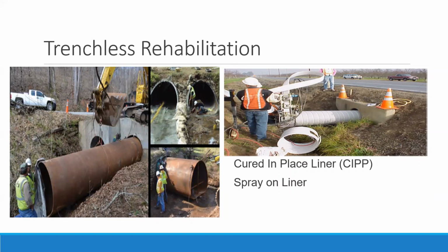Second, we've got spray-on liners. Spray lining occurs when the structure of the culvert is sprayed with a variety of different liquid products. This reline method is typically less expensive, but does not provide the structural support of other slip line methods. Spray lining materials can include polyurethane and cementitious materials. Next, we would have vinyl wrap liners, which use a specialized machine to install a spirally wound vinyl material into the host pipe. You can see from the picture here where those sections would be fused together as they pass through the machine and are inserted into the host structure.